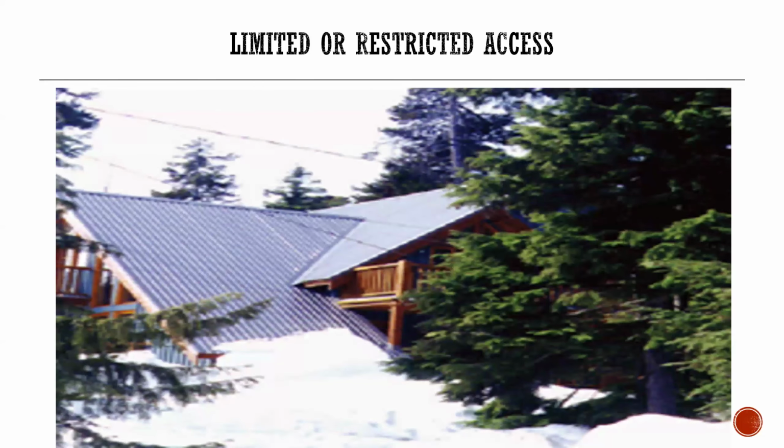Building with that snow shed in mind, such as this cabin here, we have to understand where that snow can go and how far it can go. So there's a garage on the left side of this photo and a beautiful walkway that gets you from that lower garage up to the front entrance that is to the right behind that pine tree. And that whole entire walkway and entranceway is blocked completely by the snow every time the snow slides off of this roof.